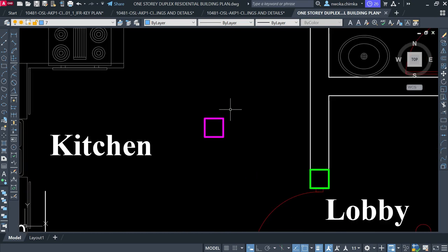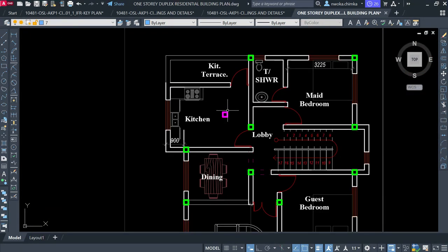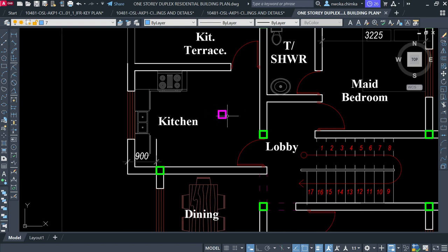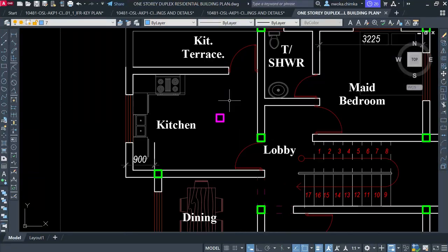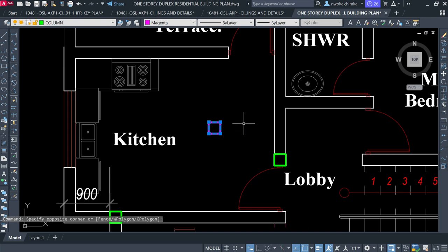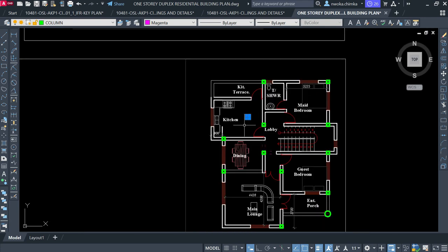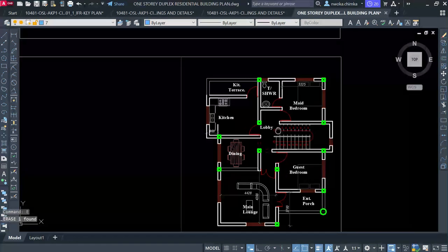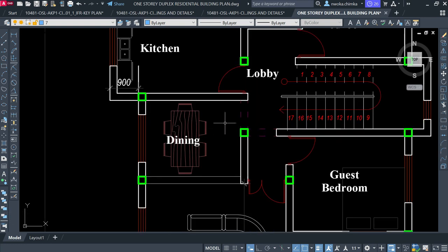Can you see that? So always change the color of any column coming out into empty space on your building, so that you will know that this color belongs to that column. When you go to that software and insert your story, you are meant to remove this column on the first floor, because it is causing what they call obstruction on this floor. But since we don't have any column doing that, I'll just remove that. So right now, all our columns are just flushing from wall to wall, as you can see. Can you see that?